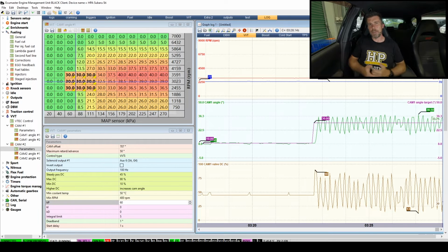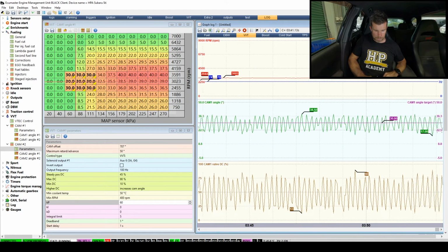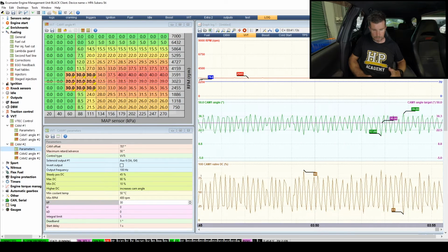So basically 30, we're probably there or thereabouts. We've got that slight overshoot or undershoot, not too bad, and we'll see if we can correct some of that with our derivative gain. So let's get our logger back up and running. We'll come back down and we'll enter our value of 30.